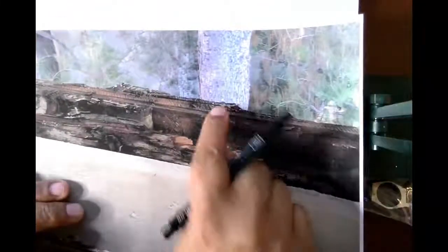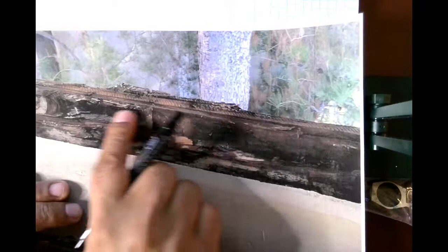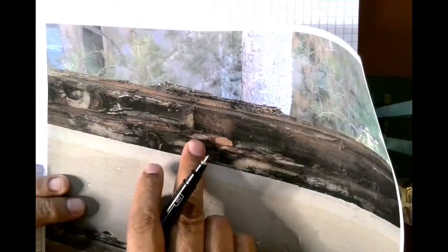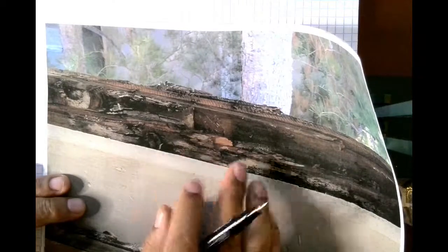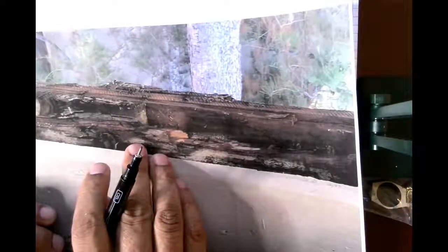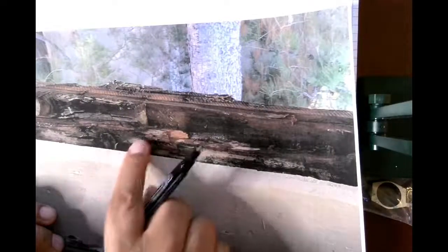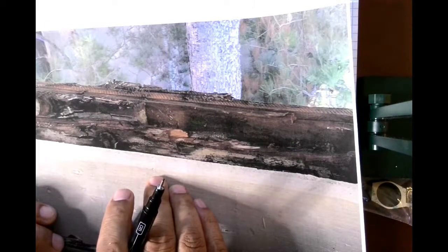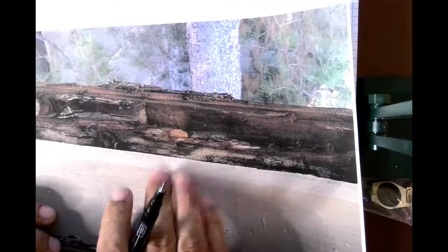And this is an example. We opened this up at a certain balcony, and what you're seeing here is the effect of dry rot. And you can't see it from the outside. When you open it up is when you see what is going on. And you can see that it's definitely got problems. And you can't fix this. You've got to take this wood out. Because even if we, this is obviously very bad. And when we remove the rest of this, you see that it gets worse. So water is your biggest enemy.